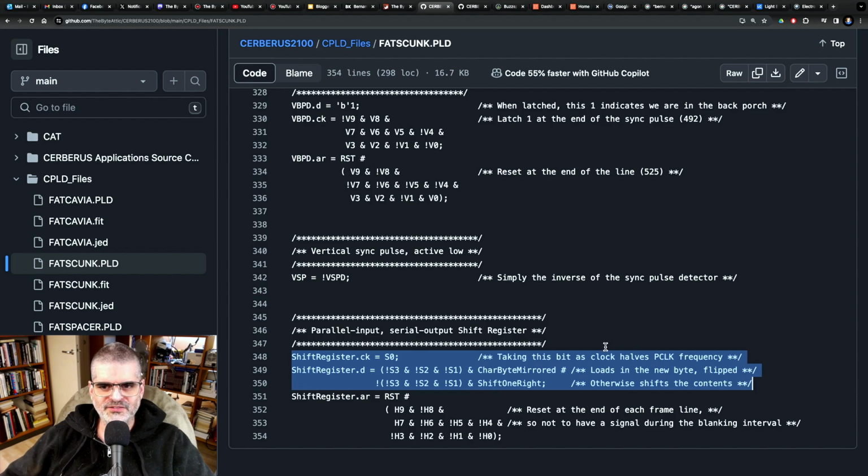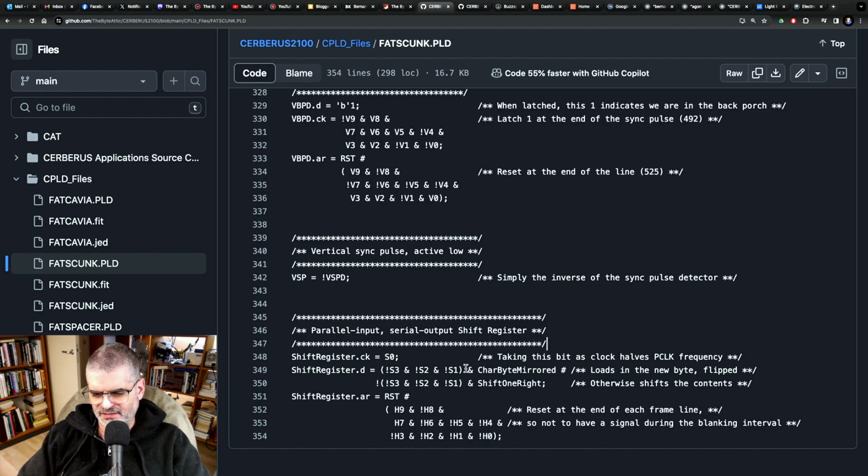Only 3 lines, you see? Super easy, super clear, and in Dutch we say overzichtelijk, amenable to overview. You can figure it out at a glance. You land your eyes on it, and you know what it's doing. See, you have the same condition here and here, ANDed with something else, and in one case that condition is inverted. Well, that's a multiplexer. You immediately see that. You immediately see which fields, which lines you're using from the counter.